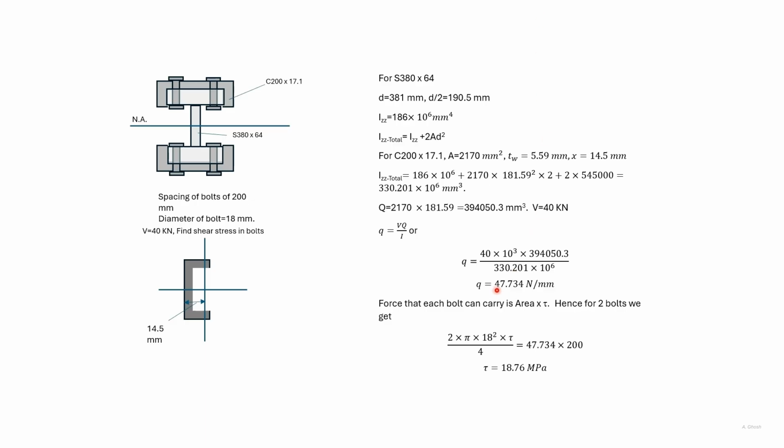The shear flow into the spacing is the force that has to be sustained by the 2 bolts. So equating, we get the shear stress in the bolts.